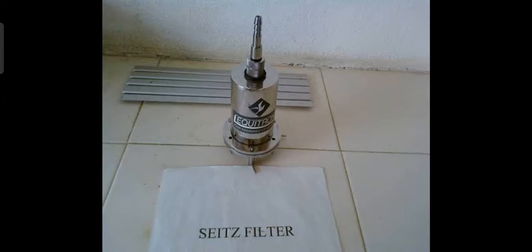This filter consists of 2 to 6 mm compressed asbestos fiber filter sheet. A variety of filter sheets containing different pore sizes are available in discs or squares, ready for use and work satisfactorily only for a few hours. The medium to be filtered is poured into the funnel-like structure and drawn through the filter sheet by vacuum. When the filtration is complete, the filter sheet is discarded and the filtrate is obtained.